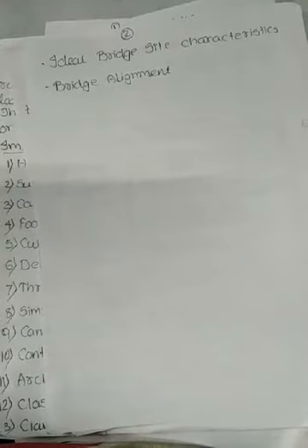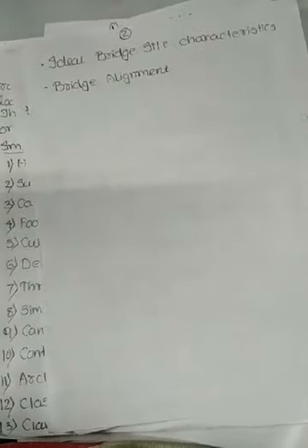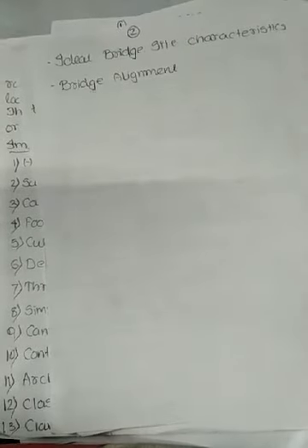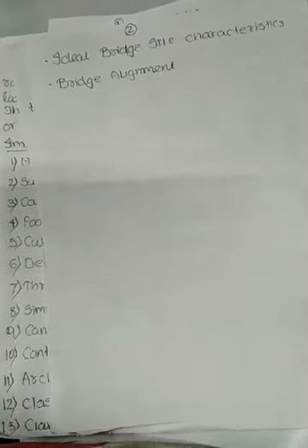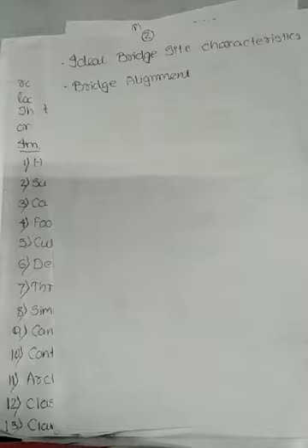Next, there should be reasonable proximity to direct alignment of the road, that is, avoidance of long detour. Next, the bridge site should be such that adequate vertical height and waterway is available underneath the bridge for navigational use.